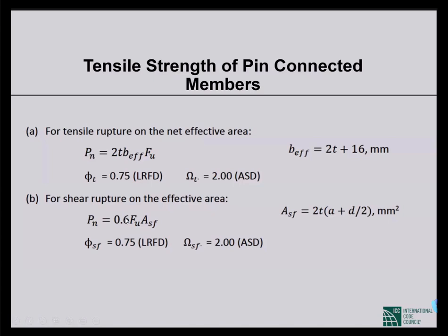For any shear case in AISC, you'll find this factor 0.6 wherever there is shear stress, because this is the failure criterion if we consider shear stress. If we have only axial stress, that's a one-dimensional case, so we can calculate the yield stress, right? Because we pull a rod and find out the yield stress.